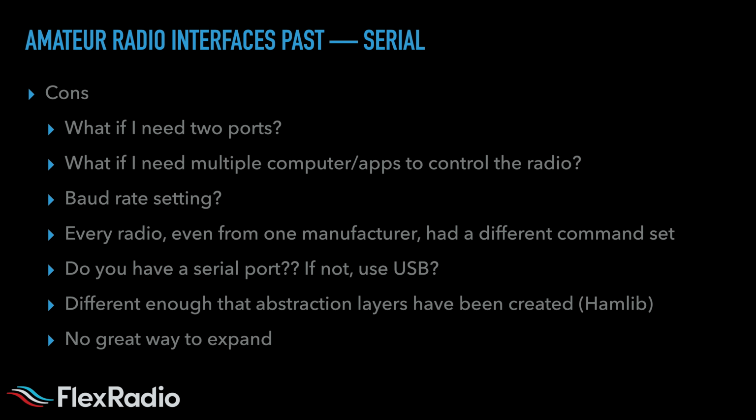You also have to worry about baud rate setting. This is not a huge deal, but you've got to check the baud rate in your computer and on your radio and make sure they're the same, and the parity settings and all that, like any serial port.